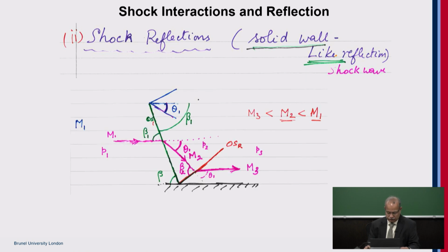And yesterday we looked at the situation of what will happen if an oblique shock intersects a solid wall. When a flow encounters an oblique shock, the flow will turn. If there is a solid wall there, if there is no intervention, the flow will go and hit the wall. So the oblique shock will be reflected before that, so that the flow that encounters the oblique shock will turn exactly with the same angle, and then it will go parallel to the wall.